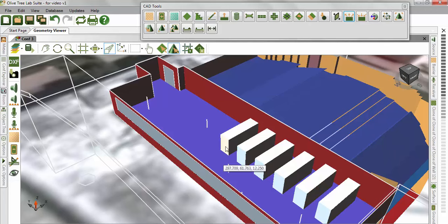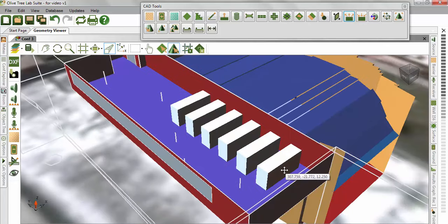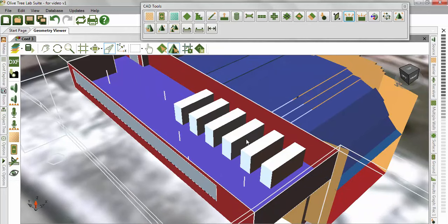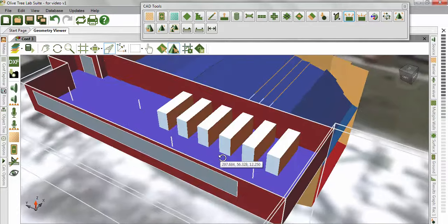We will now select them all and ungroup them to assign different properties to the different sides. Note that you can actually only need to do this once for the first bookcase before cloning, and then by cloning it, it will clone the exact parameters that you have chosen for the first bookcase. But we wanted to do this the long way around just to demonstrate the various options. Select the sides of the cases representing the books and group them, and do the same for the rest.